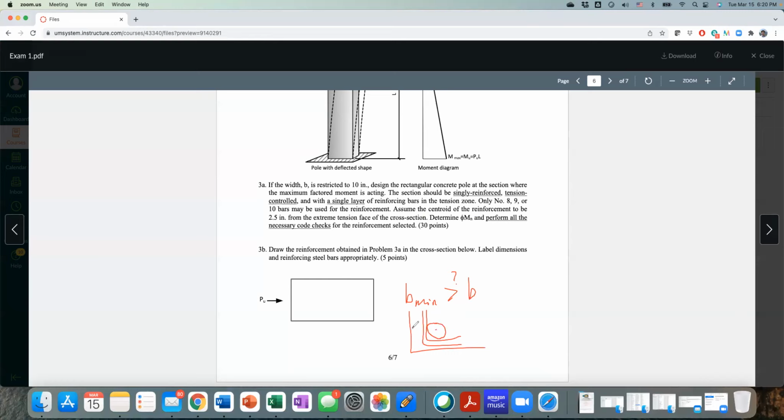Basically, what you're trying to do is you have the concrete cover, right? This is called clear cover. You can find it from the ACI table. And then you have another thing, it's called the stirrup size. So 3/8, right? Then a number 3 bar is 3/8. And then you have a bending radius of the bar, right?